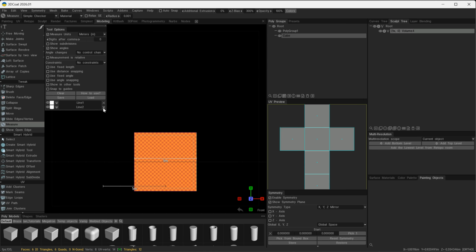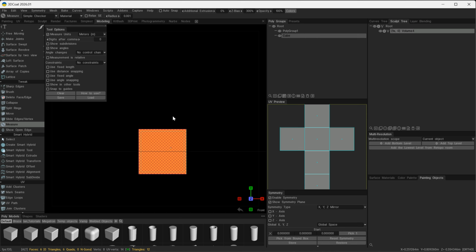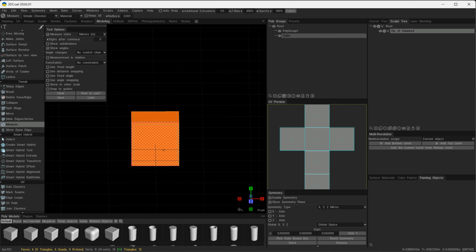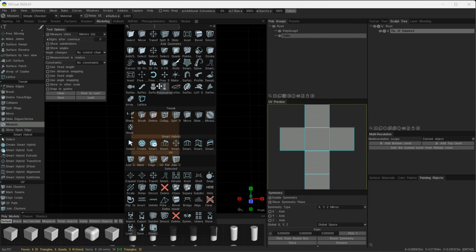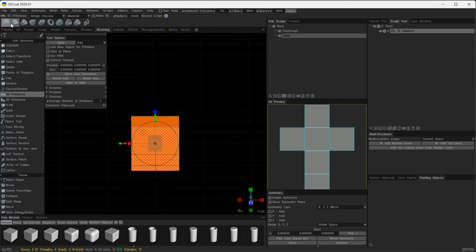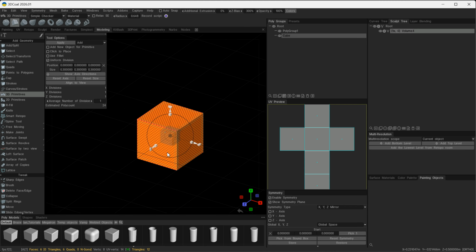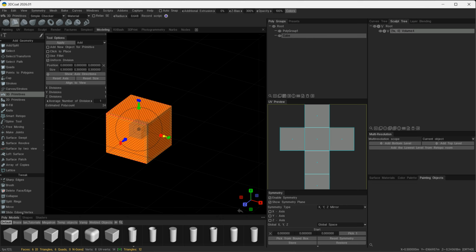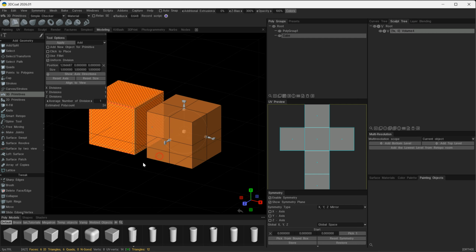Okay, let's remove those measure lines on there and let's create a new object now inside of 3D-Coat and move it back into those other programs. So I'll go to spacebar and I'll choose 3D primitives and I'll just choose a cube again. And you'll see now, if I just drag this over here, 3D-Coat places the primitive in at this small size, and the size it's bringing it in is 0.3 of a meter. So I need to change that size now to 1 meter.